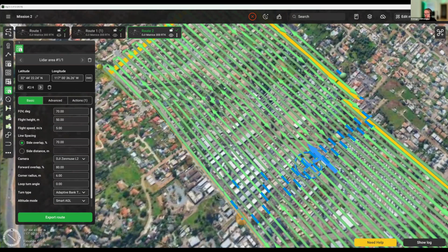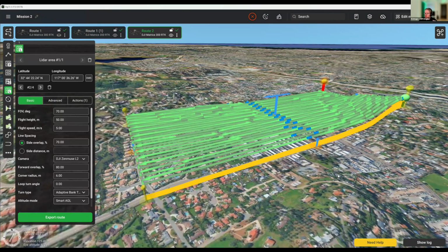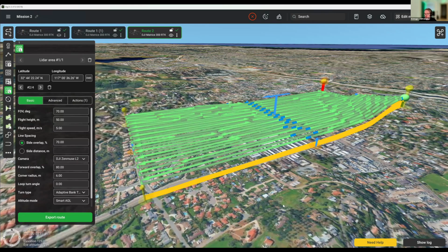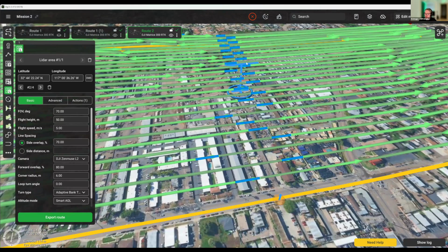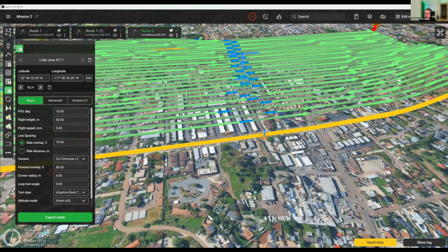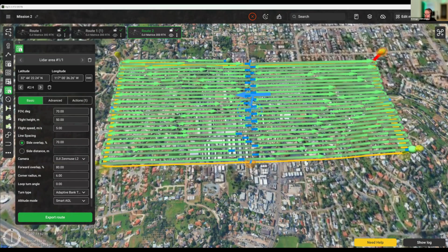So when you have these longer lines where the drone is flying without any waypoints in the middle, without any altitude changes or changes to its gyros, then here you can see that the software does add these IMU calibration segments in the middle, just to ensure that the IMU works as expected. And this behavior is the same as what you would see in the DJI Pilot 2 app. So this is the same for the L2, the L3, and for the L1, since it has to be calibrated a bit more often, it does add these segments slightly more often than for the L2.